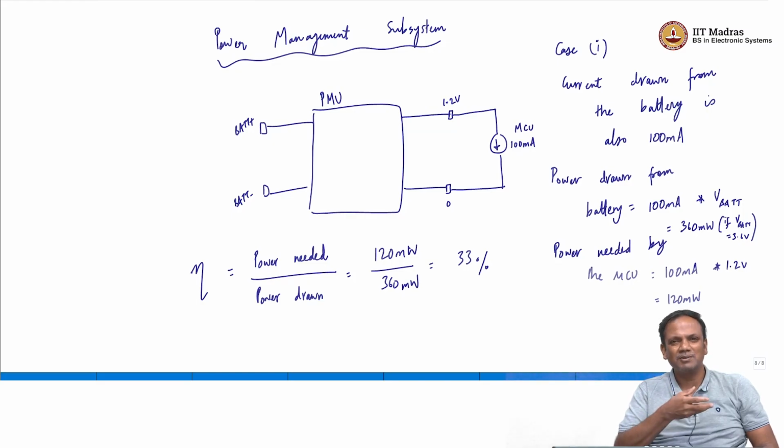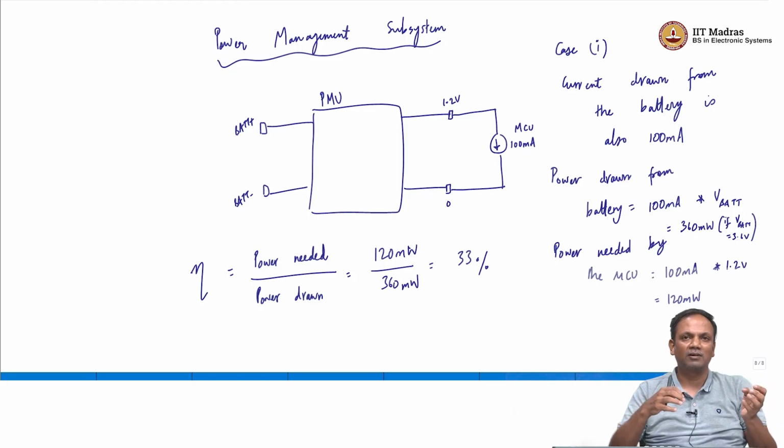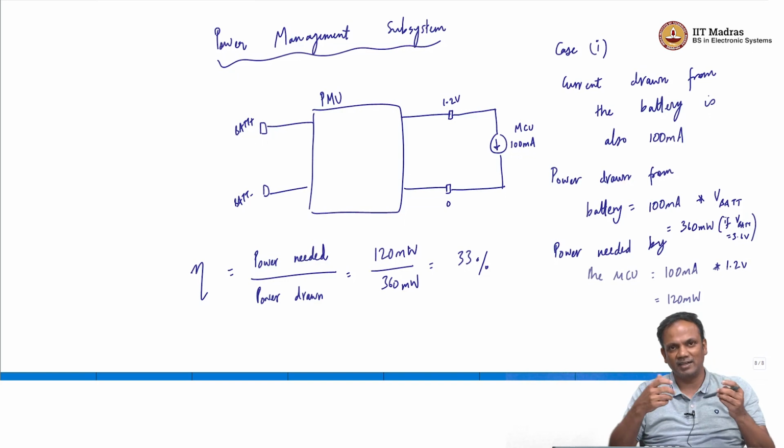So, can I put some simple regulation or a regulator circuit that only takes care of the voltage difference. Current, there is nothing happening. I am just going to supply that same current from the battery, but I have a mechanism to take care of the voltage difference. What you would be doing in that case is trading off simplicity for efficiency, right. And that is what this calculation sort of shows, that let us say the current drawn by the microcontroller has to be completely serviced by the battery without any attenuation,